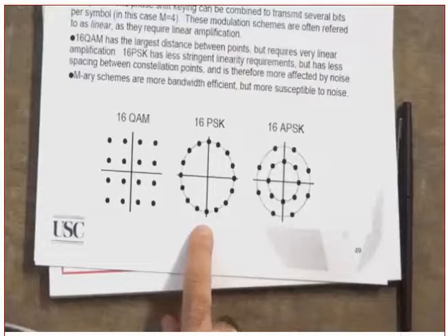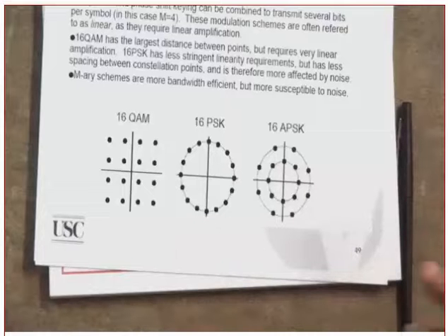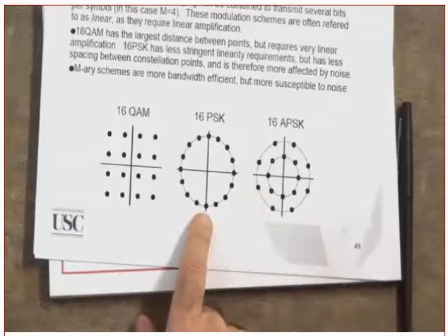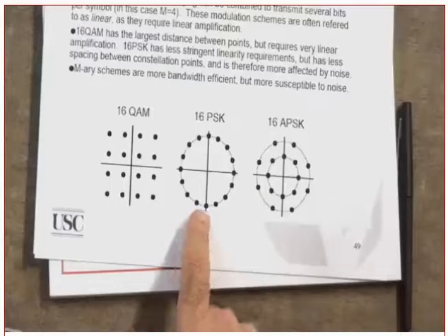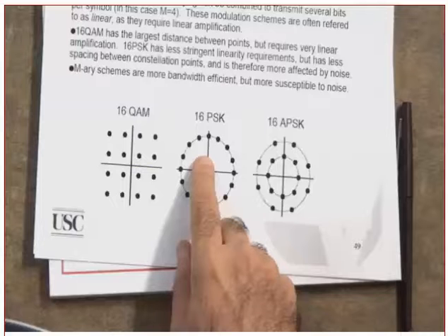4 bits per second per hertz. Do not say 4 bits per hertz. It's 4 bits per second per hertz. Did I improve the bandwidth efficiency? I improved the bandwidth efficiency, but at what expense? At the expense that the bit error rate has increased.